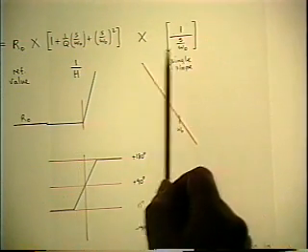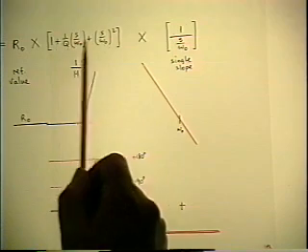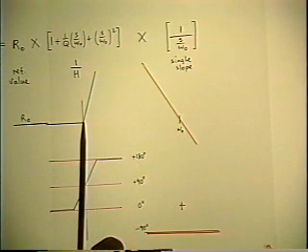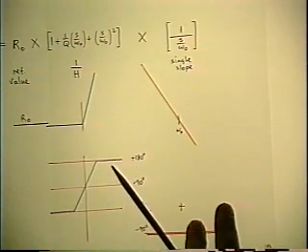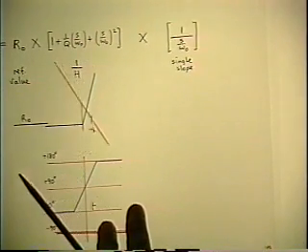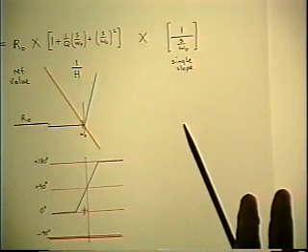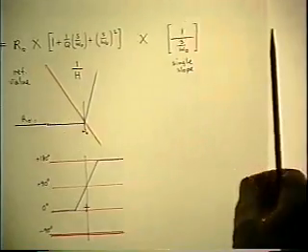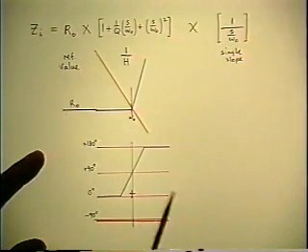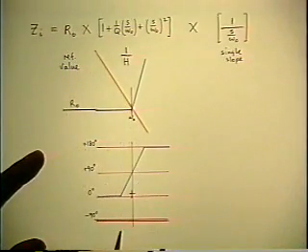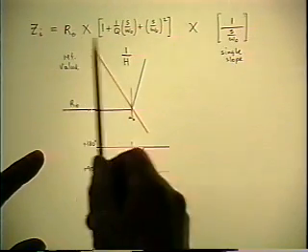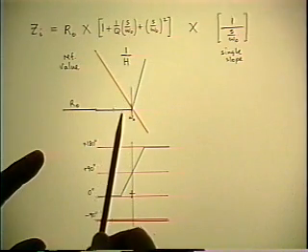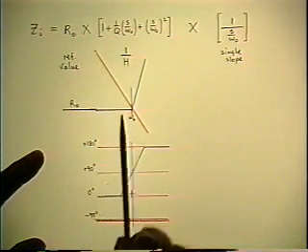But this is the same omega 0 that I've already incorporated in the quadratic, and I've located that at the corner of the quadratic function. So I have to move this picture over until the omega 0s line up also. So now I have everything in the appropriate relative position, and since I'm going to multiply those three functions together, I simply add the asymptotes on the log scale.